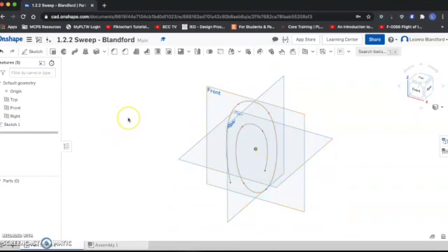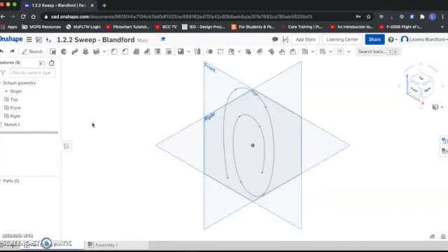But we can't do the sweep tool quite yet, because the way the sweep tool works is it needs to have a predetermined surface to generate from. Okay, so before I can use my sweep tool, I actually have to add circles to the points on my sweeps. That way it has surfaces to work with.